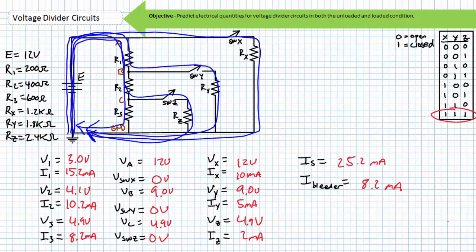Please take your time to revisit any calculations that may be in error and pause to consider the general guidance I issued before giving you these answers. Visualize circuits at the nodal level and from the perspective of flowing current. Elements within the same path must have the same current. Paths in parallel must have the same voltage drop across them.